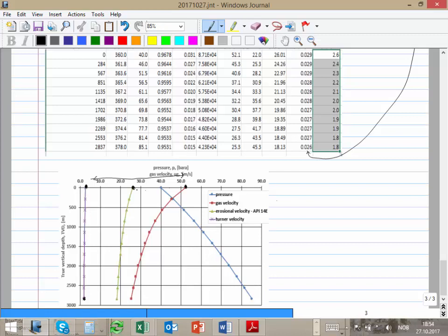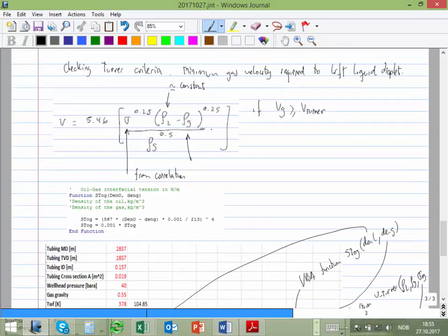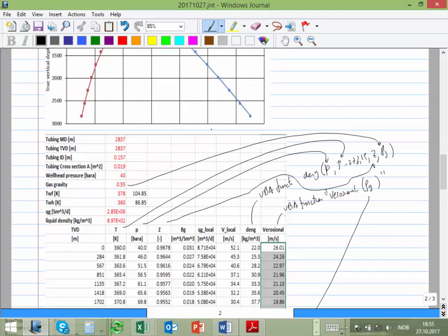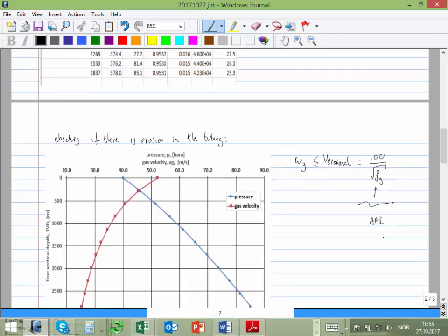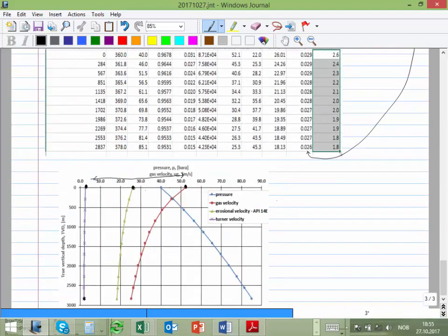What are we doing then to make the other conditions meet the diameter of the pipe? Yeah, you have to reduce the rate of the well, basically. If you want to use the same well, you have to reduce the rate. Also, some people say that this API criteria is too conservative, because remember this equation came from API. They say it's too conservative, so they recommend using another C which is higher. So maybe if you relax the C, you might be able to produce it. But at least using the API equation, that's what it gives us. We're not changing the pipe?